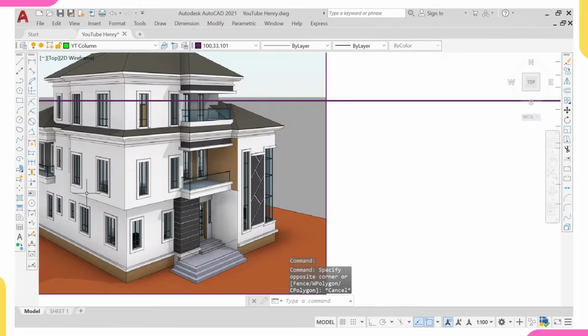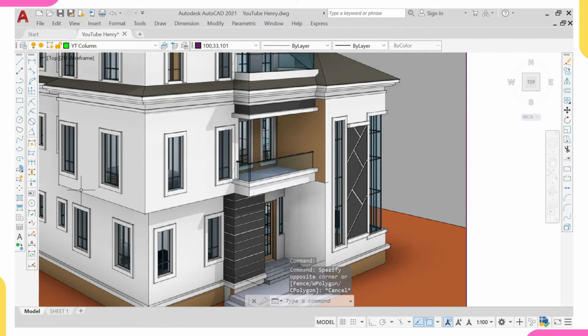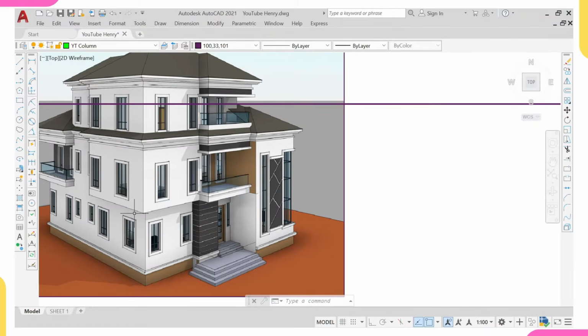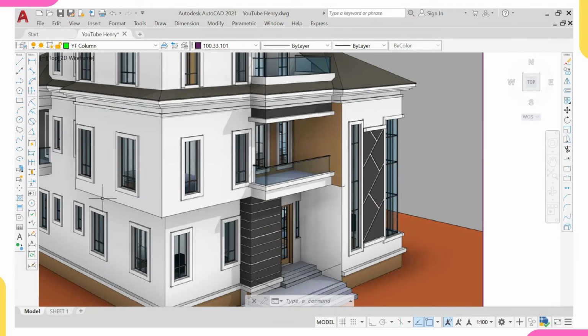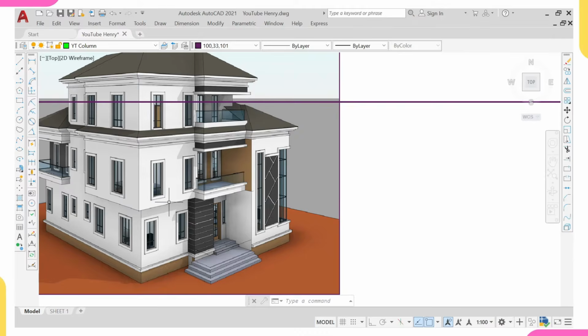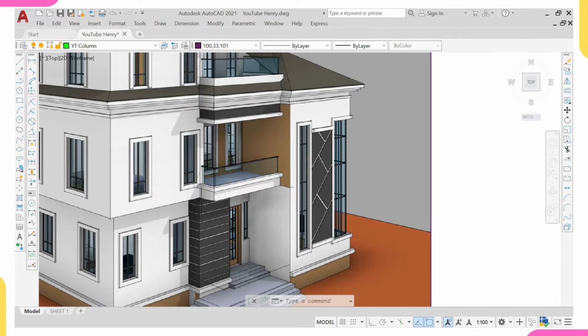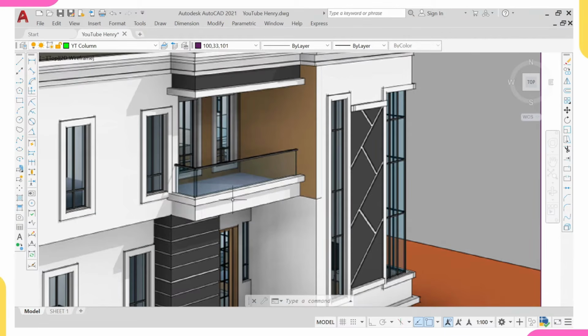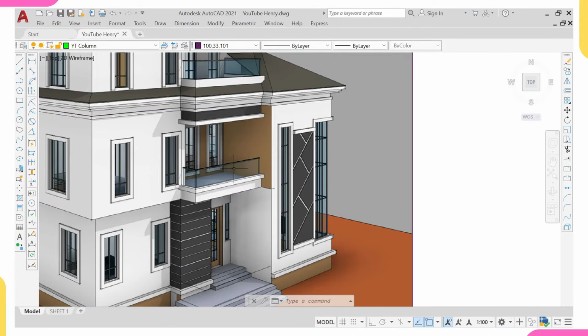These ones are carrying wall load. Yeah, it can carry it. Highest, the space will be 200, but it's carrying wall load. We'll make the spacing 200. Why this one is not really carrying anything, and the length is 1,600. So it's good to go. So far it's carrying only the handrail. We are good to go.